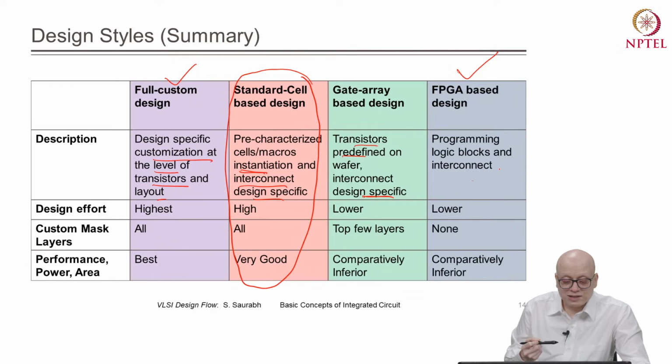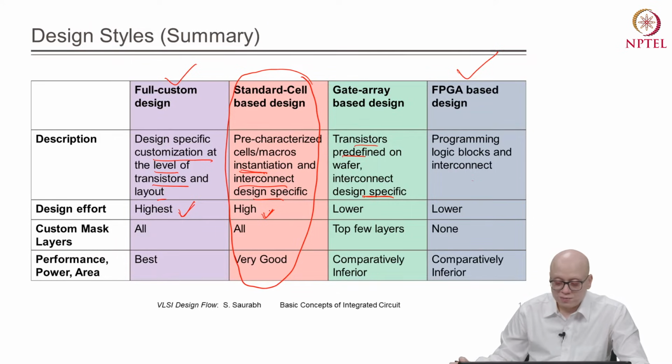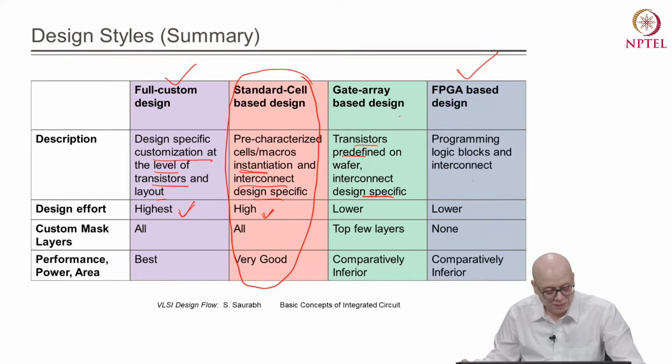Now in terms of design effort, the full custom design requires the highest effort. Standard cell based design will also require a high effort, but less than full custom design. And gate array based design and FPGA based design require lower design effort.